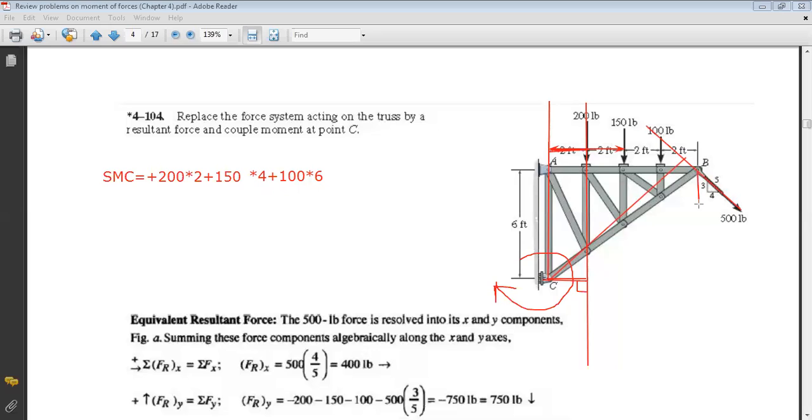So you can divide your force at B into two components. Already you have divided the force, so you have a y component. For the y component, the moment is clockwise and the distance is very simple, it is 8. While for the x component, who will tell me what is the moment of the x component about C? First, what is the distance?